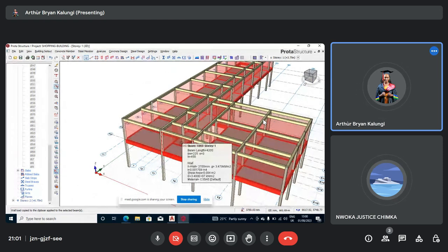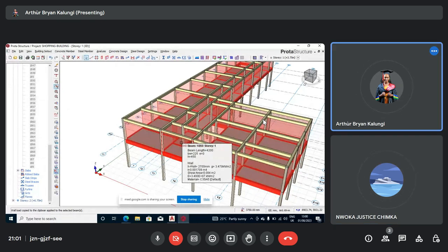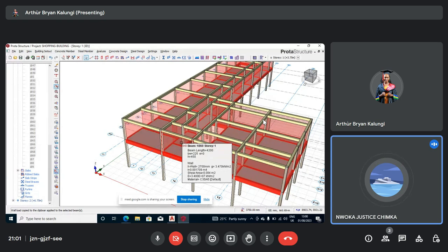Yes, I'm coming. Don't worry. We will have to go and remove those ones later manually. Okay. So right now, escape now and go to plan view of story 1. Let's go and remove those places that are not having wall loads.